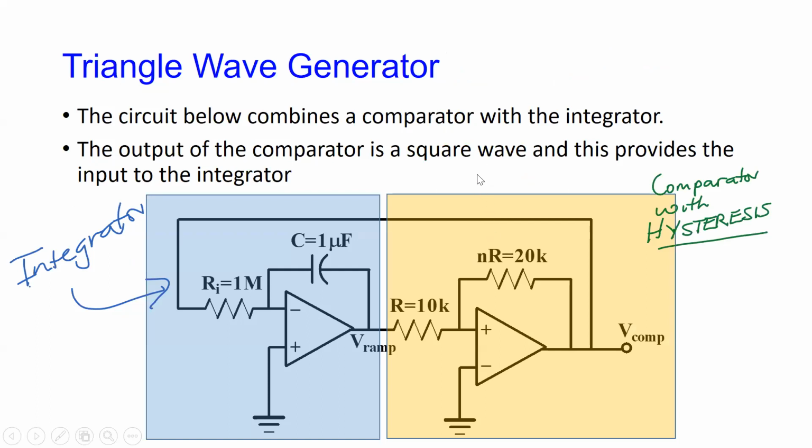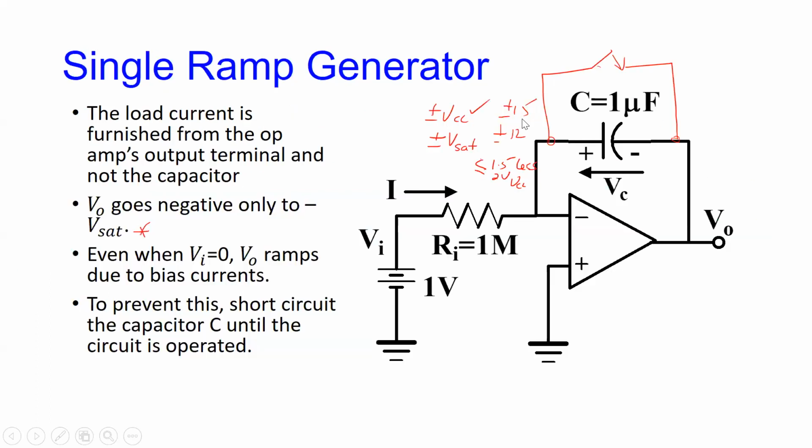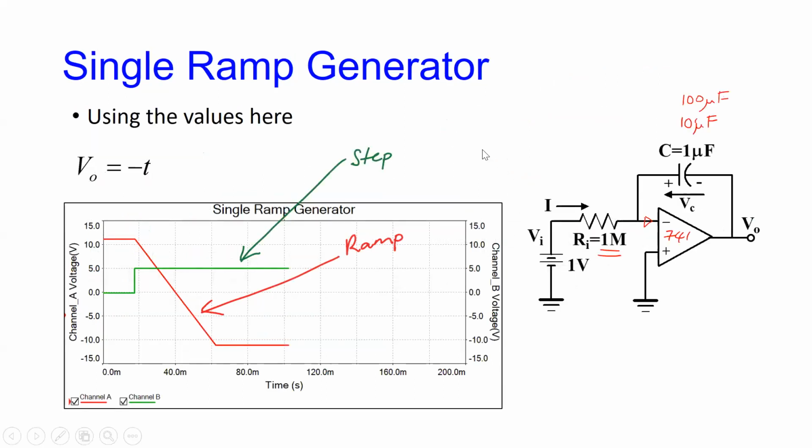Right. So the other one now is that if I put the op amp like this, and at this point in time, if I had sent the VCC back down, in other words, if after I've put this step on, I now ground the input, then the op amp is now going to ramp the next circuit. There's a negative going step. So it's going to integrate that and it's going to do this.